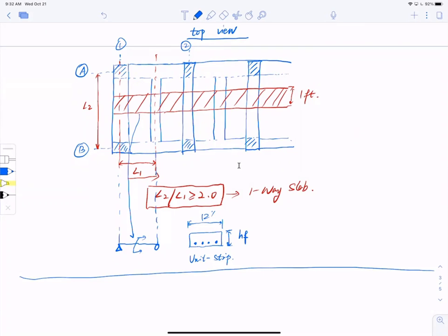But we need to provide what, right? Typically the height of the slab, or the thickness of the slab, is given. You know it. Why? Because there are so many constraints. I need to satisfy the height of the slab. For example, if it's a parking garage, I cannot afford to have a height that's so big, so it will cut into my capacity. So this is typically provided.